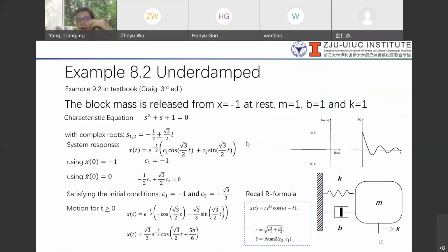All right, so under damped, the same thing. So I'm gonna go slightly faster. Just now I actually guided you step by step, plugging in all the numbers, and now this will be the same thing, except that of course you won't know it's under damped until you work out the characteristic equation and you realize that your b squared minus 4mk is actually smaller than 0.